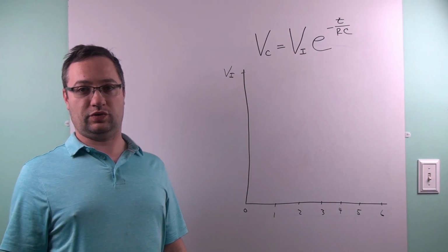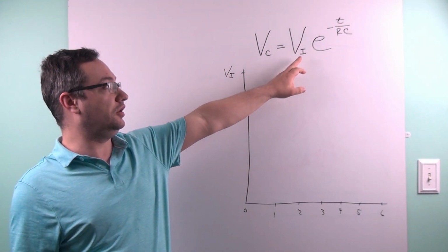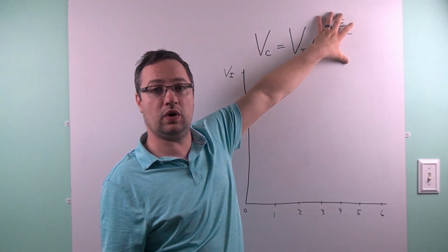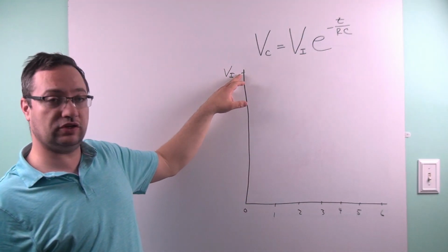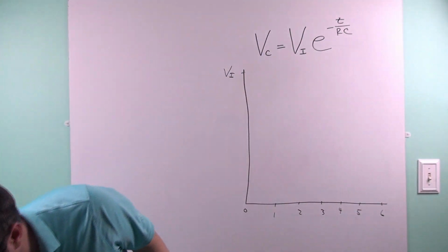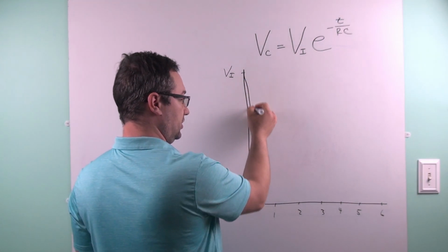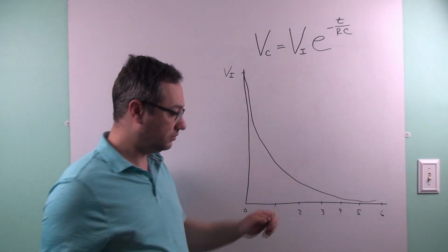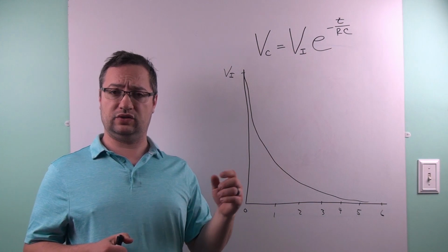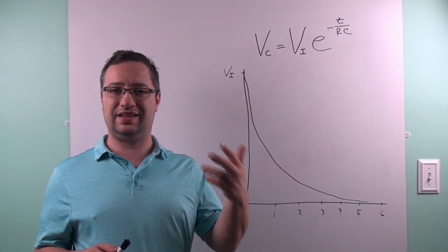And if you didn't initially recognize this formula almost right away, this formula resembles the formula for charging the capacitor, but for the current. And again, you start with your initial voltage, VI, and then at t equals 0, this becomes a 1. And as that becomes the 1, at t equals 0, the initial voltage equals your capacitor voltage. Then as t begins to increase by your time constants, 1, 2, 3, 4, 5, the voltage decays. And so very similar to the current of a charging capacitor, the voltage of a discharging capacitor is an exponential decay, without the little swish at the end there. It looks just like that. And if you can guess, the current of a discharging capacitor also looks very similar, with the exception of it's now considered negative.